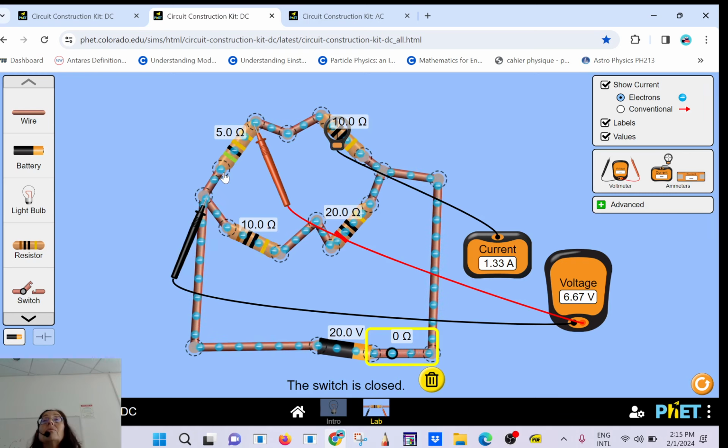Okay, so if you want to make a drawing, I think it's in the pop quiz, for a sine wave, you always have the peak value here in front. Okay, so the peak value is 170. Here you have sine or cosine, doesn't matter. And you always have 2 pi x. X will be the time, so it's the variable, okay, because it makes a function. Okay, so that will be f of x. You always have 2 pi x over the period, which is 0.02. Is that clear? So a little bit of connection with math, not that much.